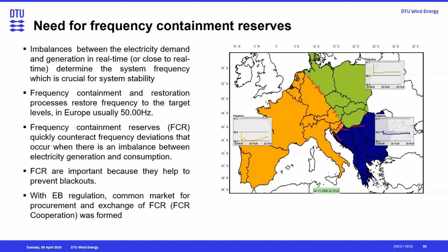In the green region, it was a windy day, but this is 2006. We did not have that much share of renewables. The renewable share was 7-8% at that time. Because of this over frequency, quite a lot of wind turbines started disconnecting, smaller wind turbines and some solar panels, and that helped in bringing the frequency back. But in today's scenarios, the new protection rules do not allow them to be disconnected.